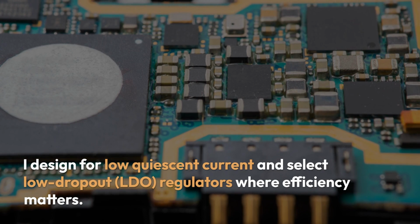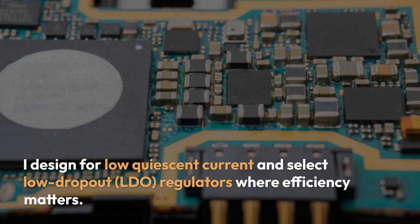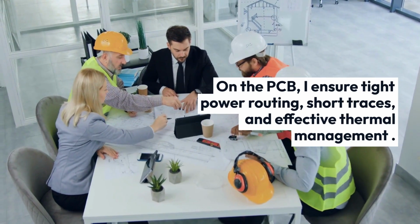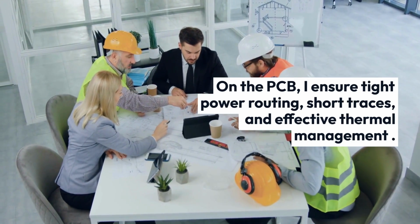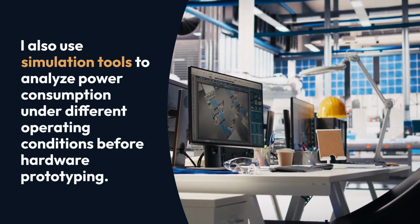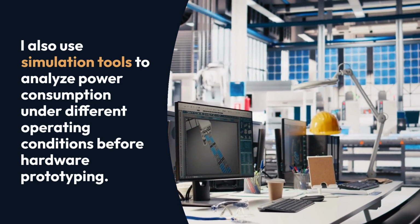I design for low quiescent current and select low dropout, LDO, regulators where efficiency matters. On the PCB, I ensure tight power routing, short traces, and effective thermal management. I also use simulation tools to analyze power consumption under different operating conditions before hardware prototyping.